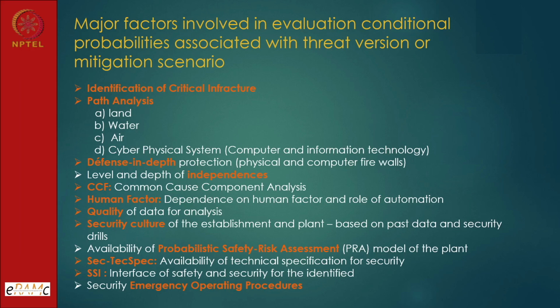Suppose you have a site: identify the critical infrastructure, because not every infrastructure is important from the point of view of damage consequences. Once you identify it, you can prepare a priority list, critical category 1, category 2, 3, 4, and effort should be spent accordingly.